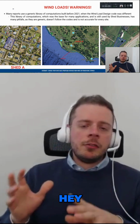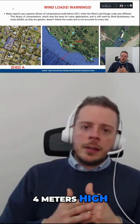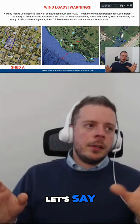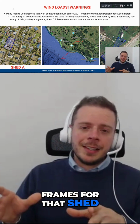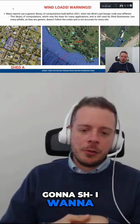And this will say, hey, if the shed is, let's say, 10 meters wide, 4 meters high, and 15 meters long, in region A, that we will, let's say, accommodate for South Australia and Victoria, then you can use these specific frames for that shed. However, that can be wrong. And that's what I want to show here.